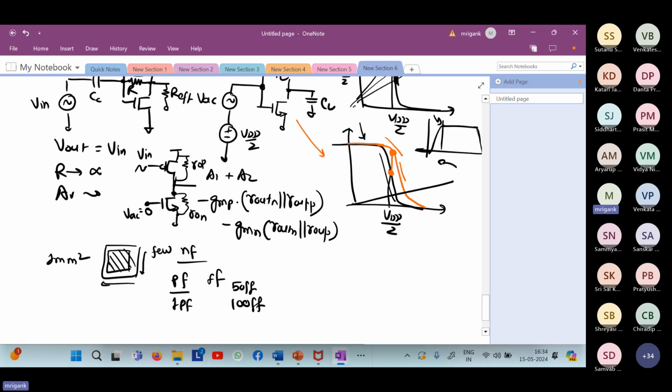But in case the previous circuit is directly coupled to this node, that means if we do not have AC coupling, then this R will also have an effect in loading, right? It will load the previous circuit. If you don't have CC at all and the previous stage is directly driving it, having a larger R will be beneficial because it will not have any significant loading effect, almost like an open circuit, right? Whereas a smaller R will load the previous stage. It will have an effective R. So I will give you some assignments through which you will be able to appreciate these points.